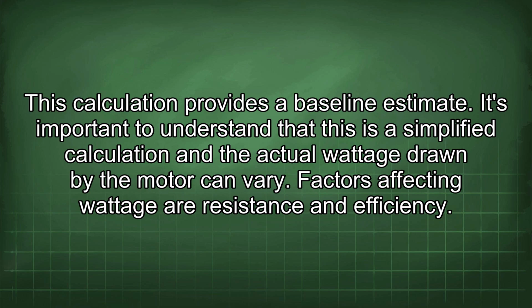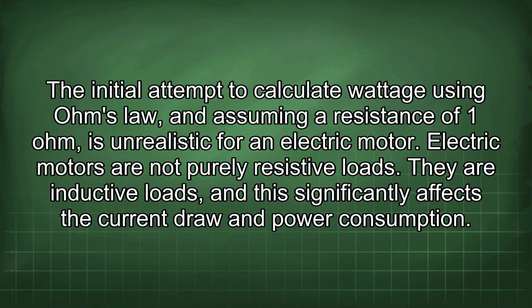Factors affecting wattage are resistance and efficiency. The initial attempt to calculate wattage using Ohm's law and assuming a resistance of 1 ohm is unrealistic for an electric motor. Electric motors are not purely resistive loads. They are inductive loads, and this significantly affects the current draw and power consumption.